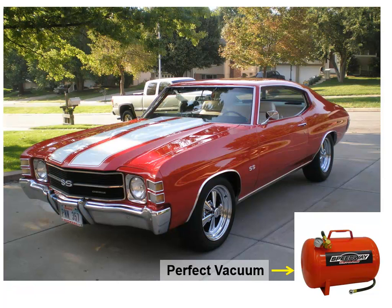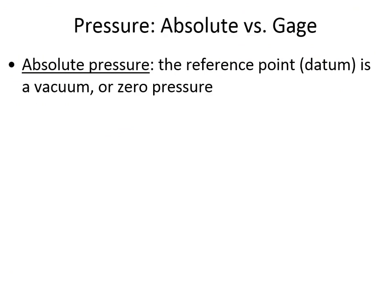It would have an absolute pressure of 0, and it would have a negative gauge pressure because it would be lower than the Earth's atmospheric pressure. Let me show you a diagram that illustrates this. Now, the definition of absolute pressure is that we're measuring the pressure relative to a perfect vacuum, or how much atmosphere there is in space.